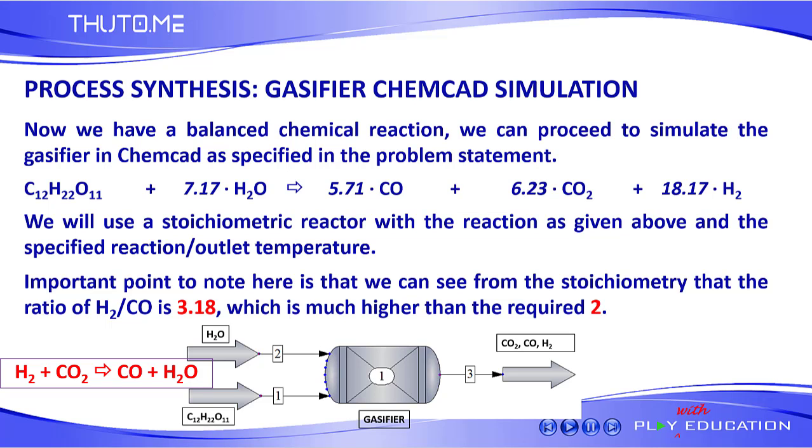Is it worth getting an extra reactor, which is the water gas shift reactor, with all its accessories, such as addition of water, maybe temperature increase, maybe pressure increase, and then the separator downstream to shift the excess amount of H2 towards making CO, so that you produce more methanol in the end?